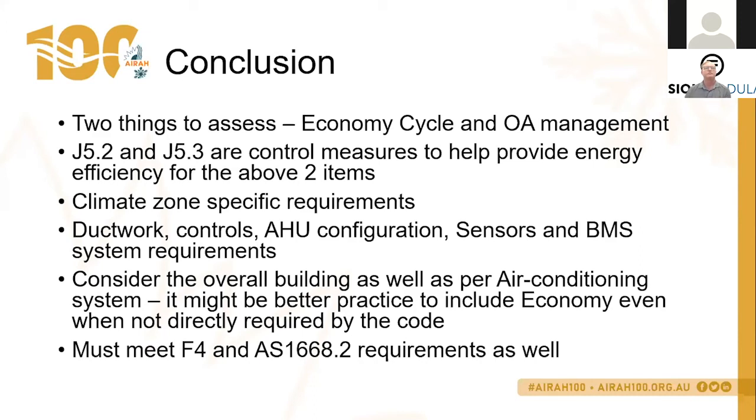What should be the minimum economy cycle enabling time? What might the impact be of this time? You need to determine that based on system design, building type, etc. What response times are appropriate for your building? I have done systems where we've made it about a 15-minute economy cycle enabling time.